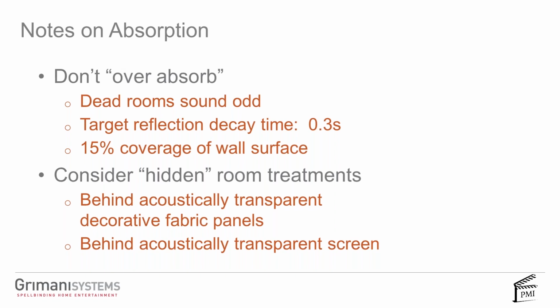It's a bunch of warts sitting on the wall and the ceiling, so a very techie client may like it if you do a very linear layout where things are very evenly spaced, which may not be the best for acoustics. It may look okay, but basically this stuff doesn't look good. Ideally, you want to hide it behind acoustically transparent decorative fabric. So you line the walls with essentially an upholstery fabric that has to be acoustically transparent.